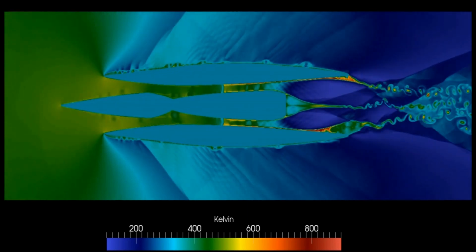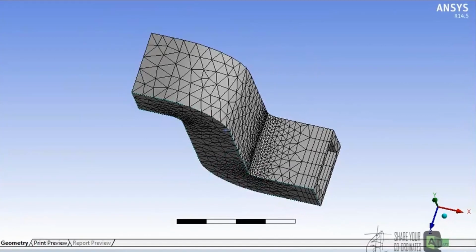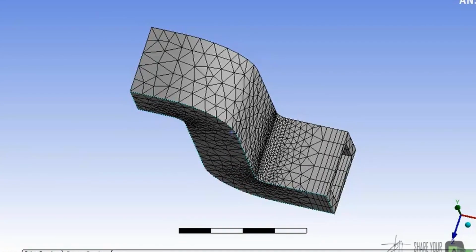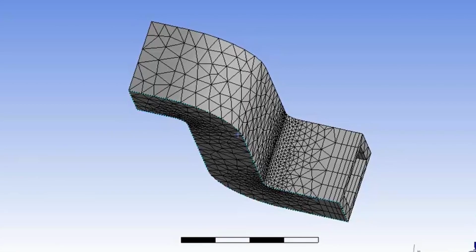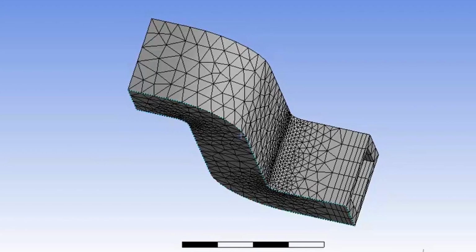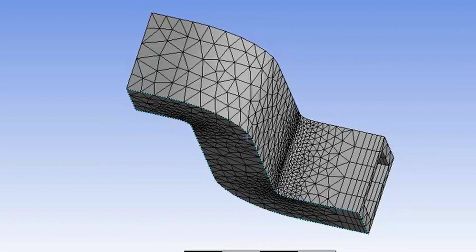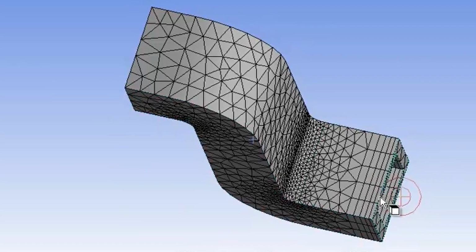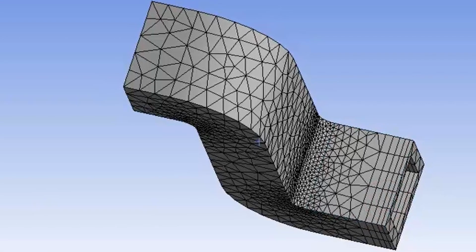Most Eulerian methods utilize mesh to describe the fluid domain. If the mesh is not changed, these cells and their neighbors stay the same throughout the simulation. Most Lagrangian methods, on the other hand, do not use a mesh but rather points that can move around freely in space, and as these points often carry mass and volume, they are called particles. Imagine each molecule of water in the river as a particle, and these particles can then move with the flow, and these neighboring particles are changing constantly.